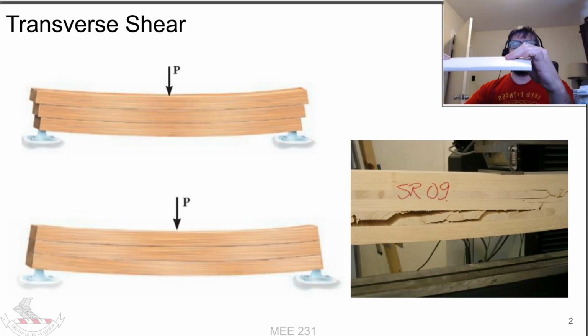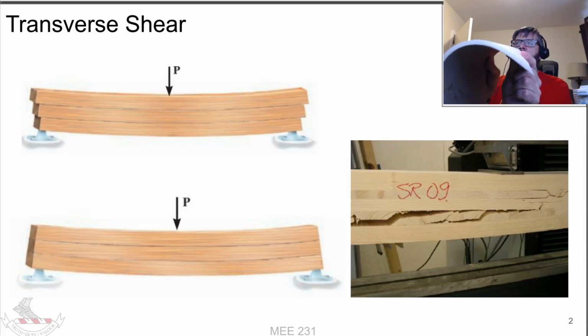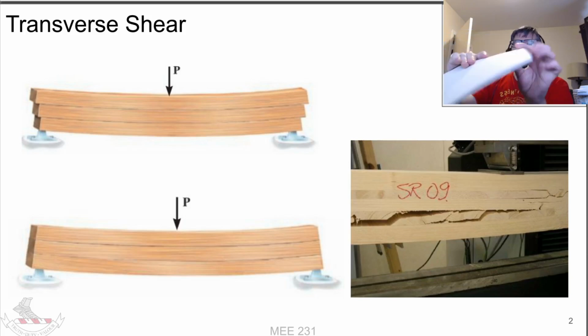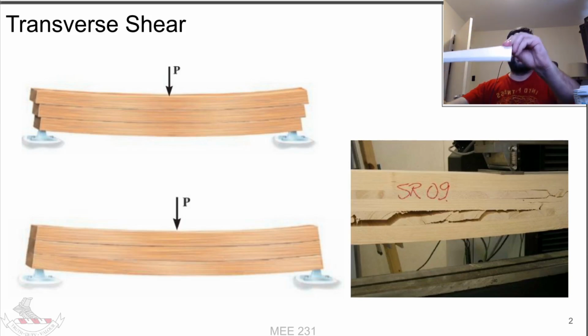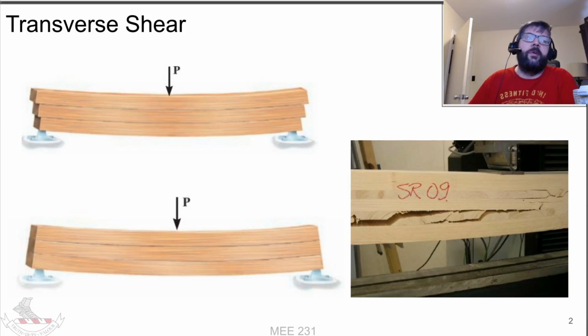We've got this engineering pad here. If I rotate this end here, you can see how at the end all the sheets are sliding relative to one another. Whereas if I clamp down on here to provide enough friction to resist the movement, they don't slide relative to one another, so it basically increases the stiffness at the end. You get the same idea if you glued all those sheets together or even just put some staples through, they wouldn't be able to slide relative to one another, which means they would be stiffer.